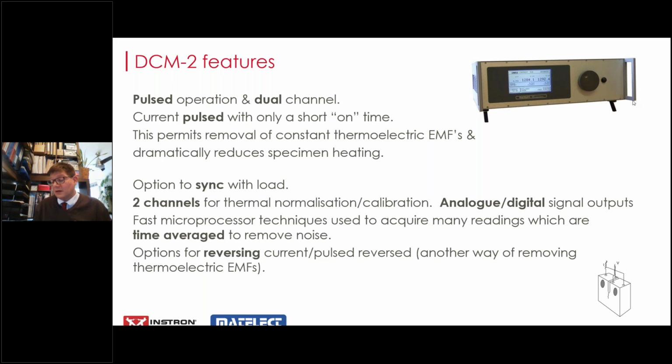While we're talking about crack opening and crack closing, there's other things which are also proportionate to the current state of the crack opening and closing. There's movement of the leads in a magnetic field, and there's also any change in the stress state of the specimen. All of these are compensated for by knowing where you are on the signal, and therefore can get a steady state value for it.